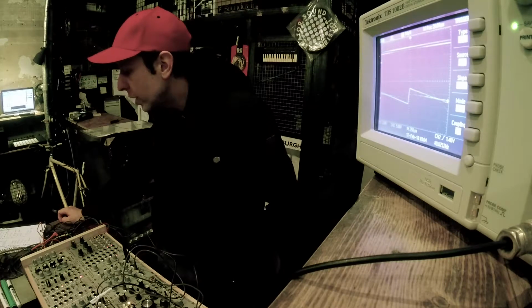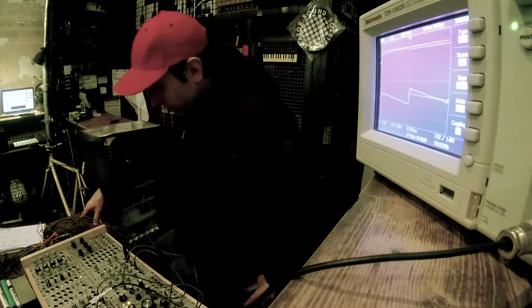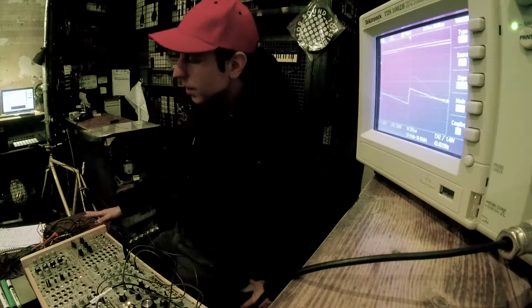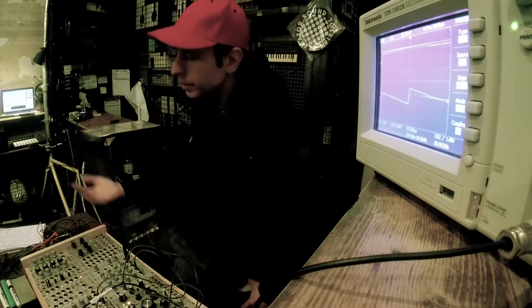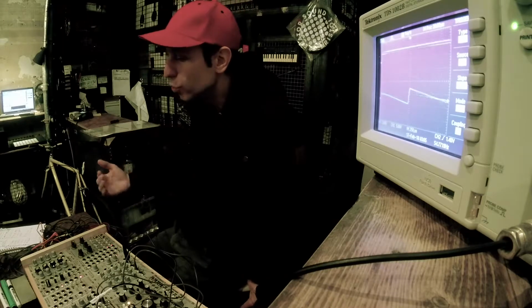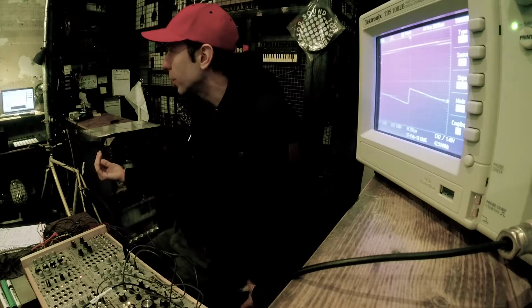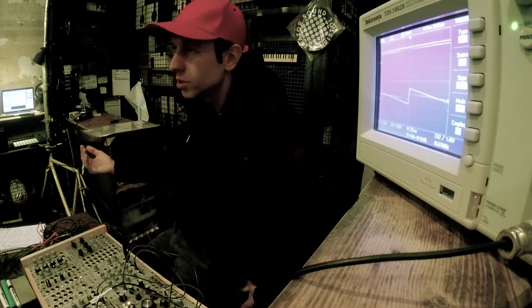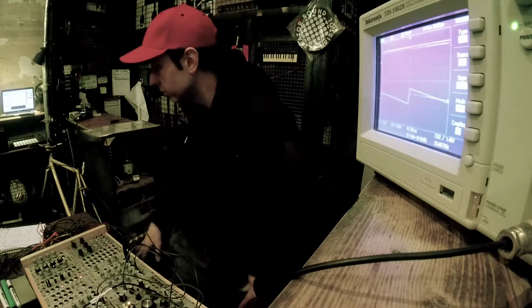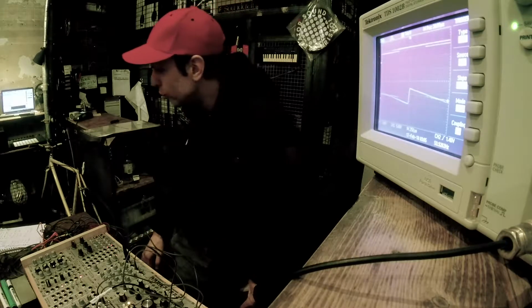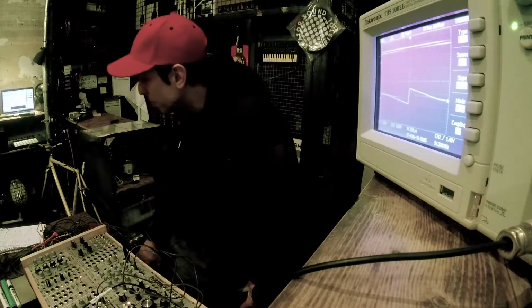What we could do is have adaptive effects. Adaptive effects are the family of effects that use a certain analysis on the incoming signal, and that analysis is used to control the processing of that signal. So you could say that our compressor is an adaptive process because it changes the gain based on the amplitude of the signal. In a similar way, we could use noise in an amplitude-dependent fashion.